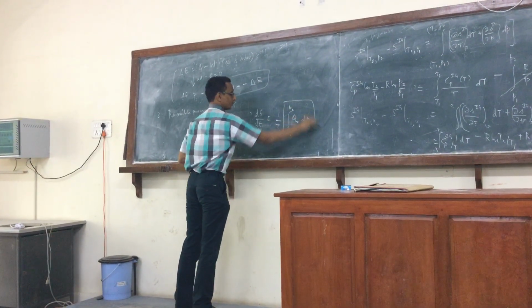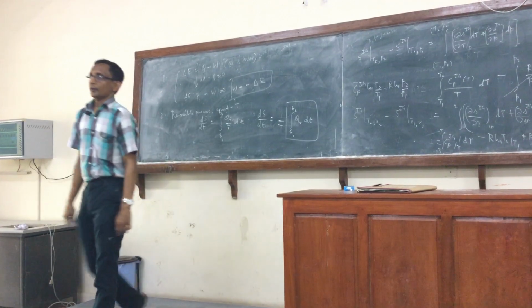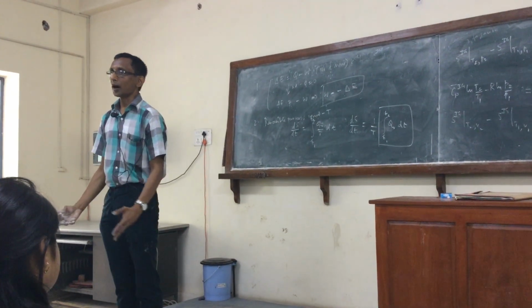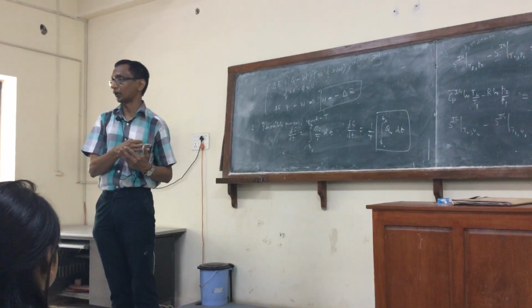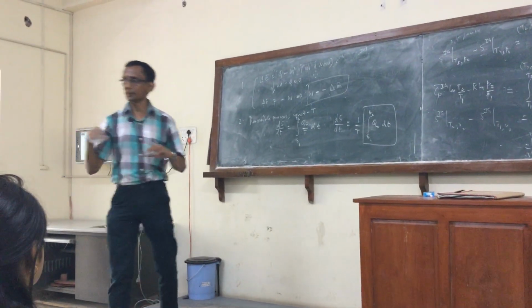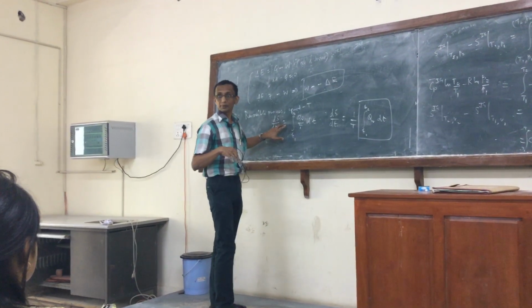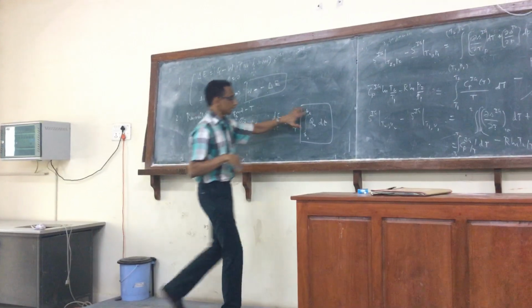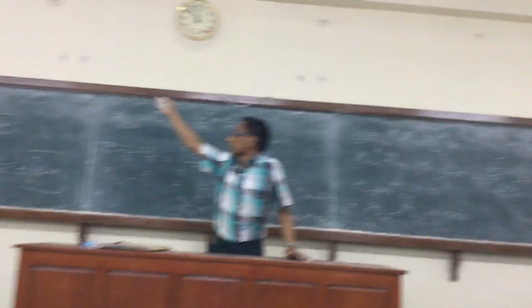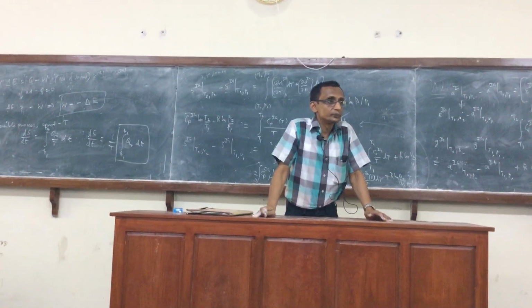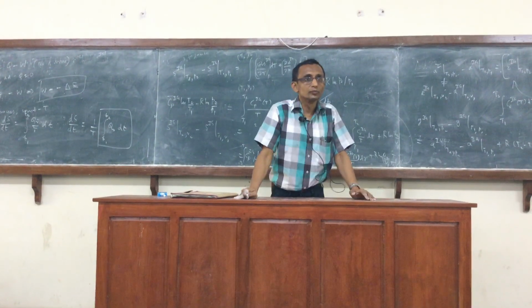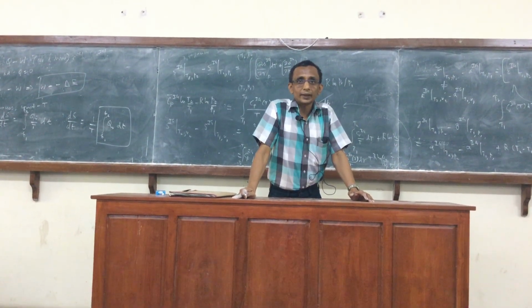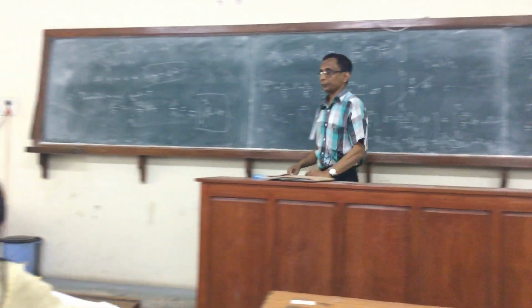Now what is this? It is 1 over T times the integral from 1 to 2 of dQ_R. Otherwise, if the temperature is changing, I cannot take the temperature out of the integral. It is a constant temperature process. And again the equality holds only for reversible; otherwise I have to make it an inequality. What can you say about the integral of dQ_R from 1 to 2, in terms of quantities that are written there on the board? What can I equate it to? What does it represent to you? The net heat input to the body over the process.